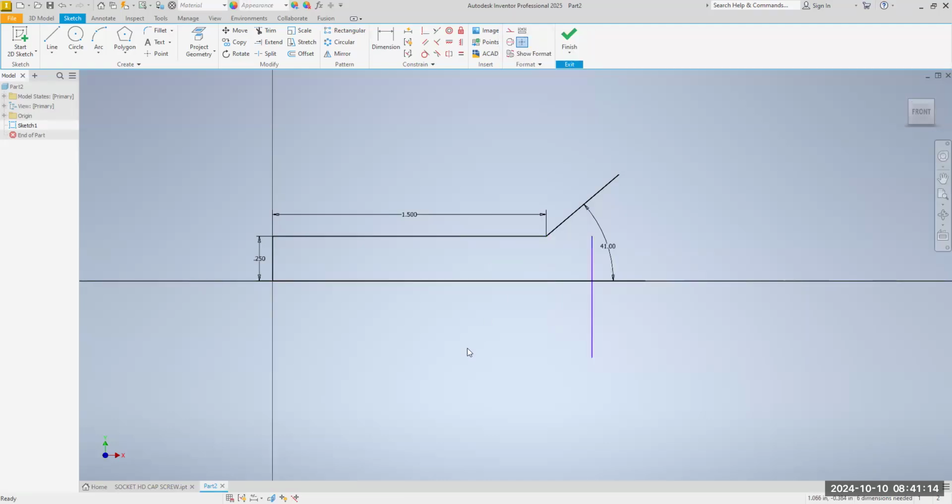You don't need it. And we need to do some extends, and I made a new word, extremes. Let's do extend here. Here's the extend button right here. Click on that. All right, so I extended that line up to this line here. Do a right click, okay. So I want to trim now. Trim this, this, and this. Right click, okay.